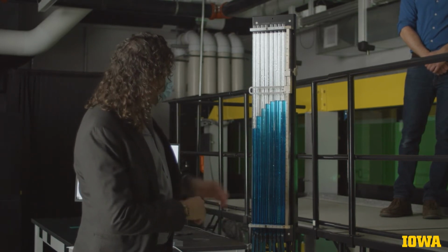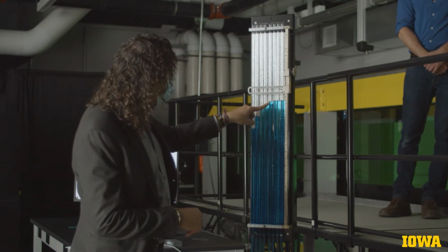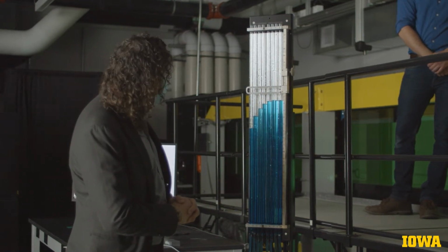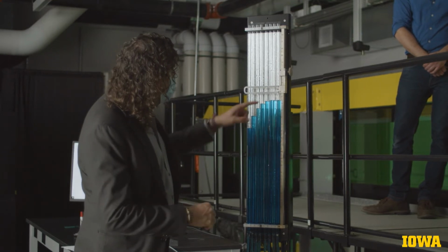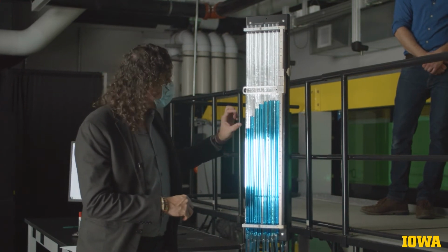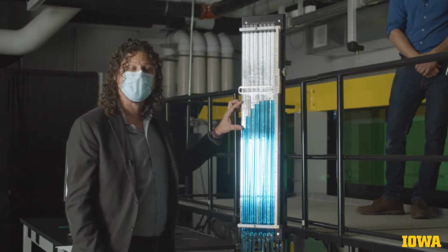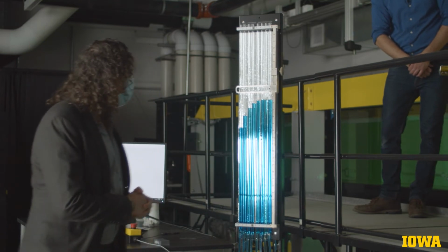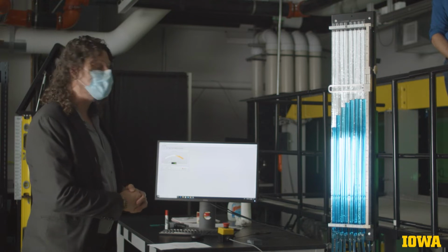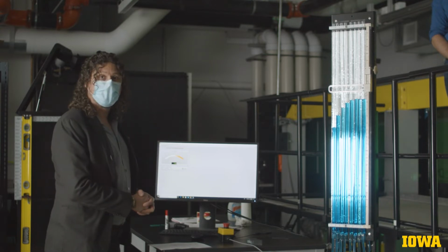As we move into the manometers connected to the gate, you see here that there is a difference in the pressure that is being measured as we go lower into the gate. And what's happening here is that the total energy is being expressed as a pressure in part, but this difference between the pressure in the last manometer and the first manometer gives us the velocity head. Finally, we will be keeping our LabVIEW open, monitoring the stream flow that is moving through the flume, and we'll keep close watch on that.